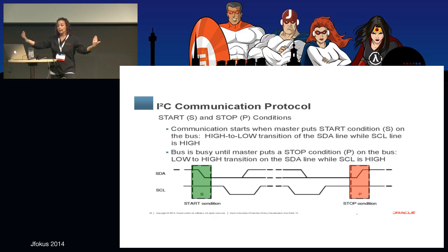The start happens when the clock line is high and the master sends a high to low signal. That means we're going to start a conversation. The conversation ends, again, with the clock line high, when the master sends a signal low to high.